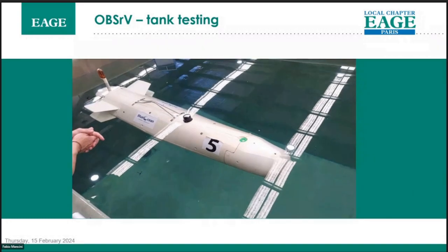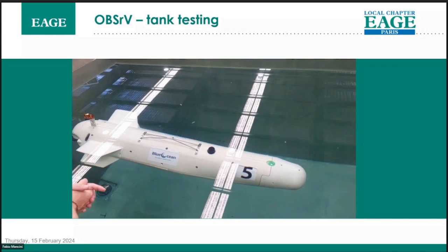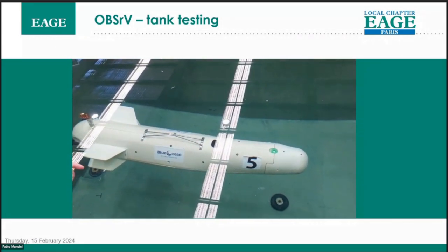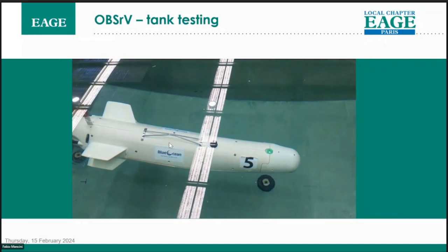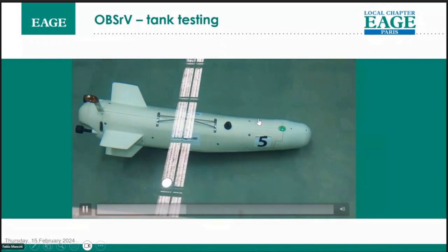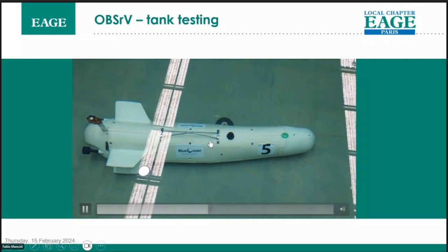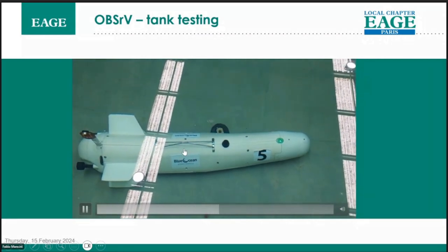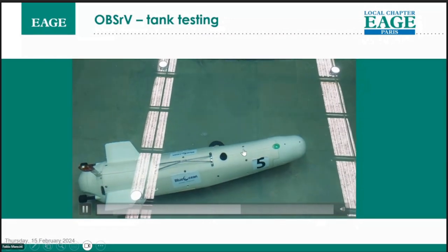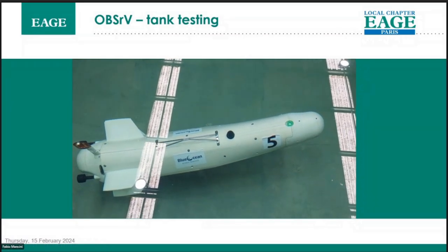For people who are not familiar with the buoyancy, I'll show you a video from a test tank where we are pushing the oil from the outside into the reservoir inside. So the unit becomes heavier because these two parts get filled with water, which is heavier than the oil. Now we do the reverse. The oil is pushed from the internal reservoir into the two bladders. We expel water, and the unit becomes positively buoyant and starts to emerge again.